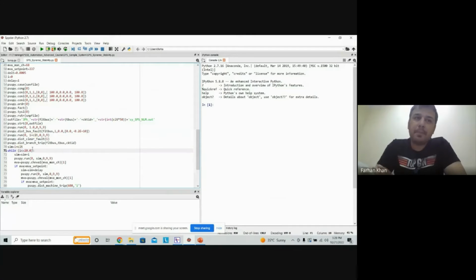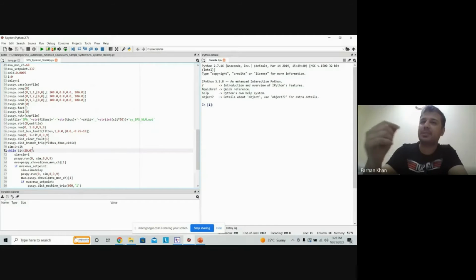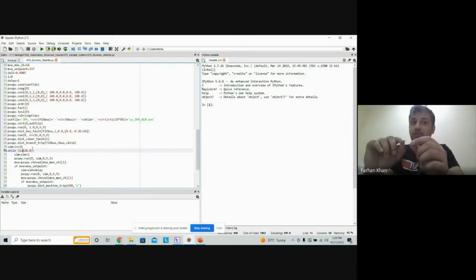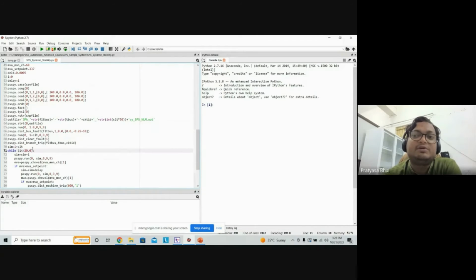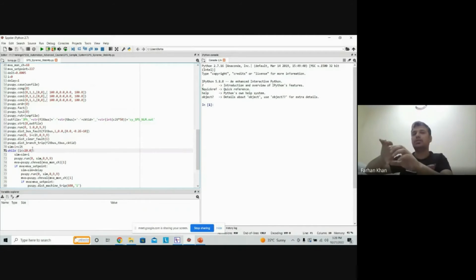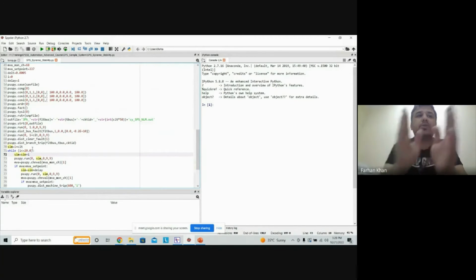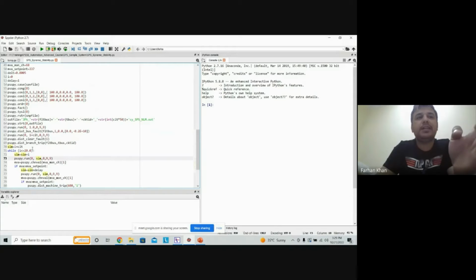So what I'm doing here, while my value is less than 20, this simulation is going to run at least 20 times. It's not 20 seconds; it's while I is less than 20, so you will run 20 times. You can even create an infinite loop and break it once your condition is met. So this is totally up to you, how you want to run this simulation. Here, sim is equal to sim plus I, so I will move to the next time step within my simulation. Now my sim will be at 2.2, and I'm going to run my simulation up to 2.2 seconds.